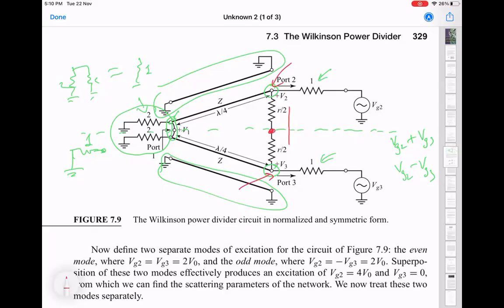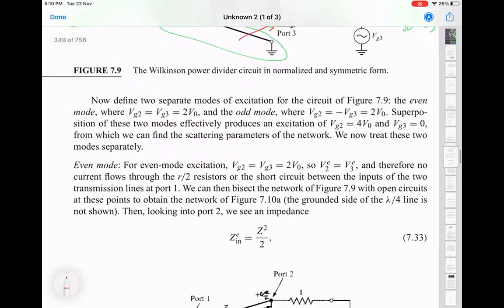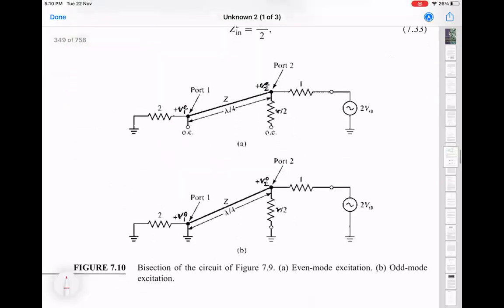That again means, instead of disconnecting it, I disconnect in a different way. I put a short there. So again, the two circuits become independent. I can analyze them, but with a slightly different boundary condition: this red point in the previous case was open, and in the second case was a short circuit. So that again simplifies the entire network, and then you can compute the responses in a simple way, which is what basically is done for the rest of the circuit.